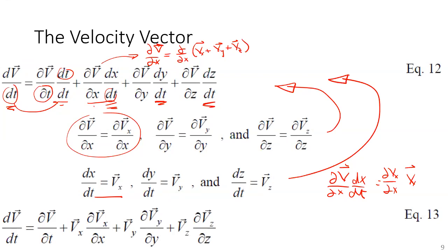Does that happen in real life? Have you ever seen a stream? You have locations of shallow water moving very fast and locations of deeper water moving very slow. That's the change in the velocity vector as you're moving in the x direction. It's subscribing to the continuity equation, Q is equal to VA. Same discharge, but as you change the cross-sectional area, velocity changes.